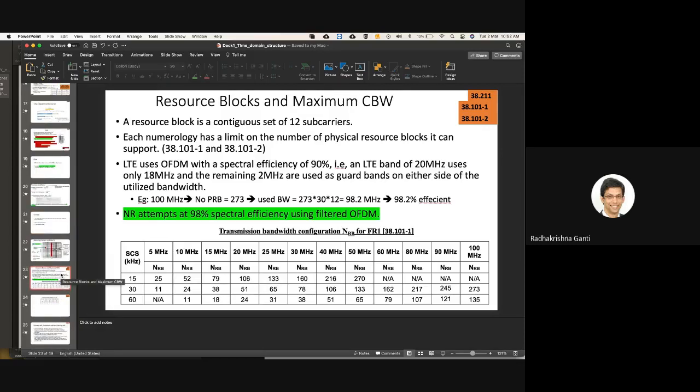But see, the main intuition was that higher subcarrier spacing will be used for higher bandwidths, and with higher frequencies you will generally have larger bandwidths. That was the guiding principle. But what Mr. Roy said was also correct: there are some limitations in terms of FFT sizes. We will do that computation. I'll tell you exactly, if you have 270 subcarriers, how you do your FFT sizes and other things.